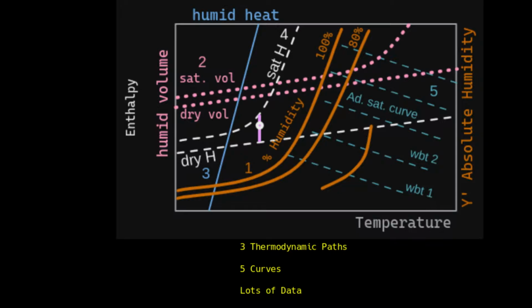If humidity y dash and dry bulb temperature are known, percentage saturation can be found by their intersection. Similarly, given any two, the third may be found. If wet and dry bulb temperatures are known, humidity y dash can be found as the intersection of the adiabatic curve at the given wet bulb temperature with the vertical line from the dry bulb temperature. This is how generally we will determine the humidity of a gas.